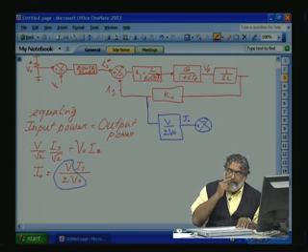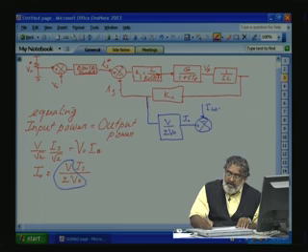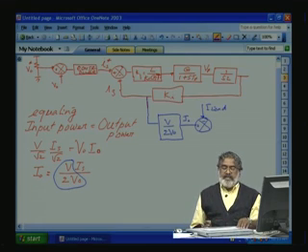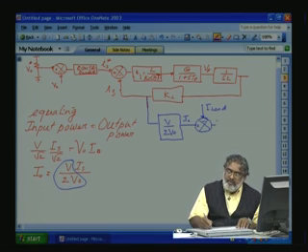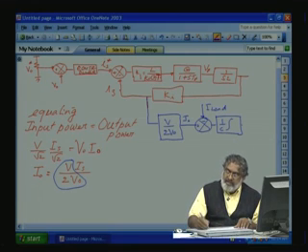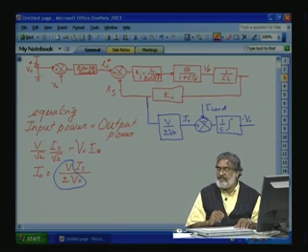Plus minus. This is our actual I load current. If there is no change, this I0 will be equal to I load, this difference will be 0 and the capacitor voltage will be stable. If any change in I load happens, the I0 flow will disturb the capacitor voltage. So, that difference will go to the capacitor and it will disturb the capacitor voltage. So, that will be 1 by C integral. That will give the V0.